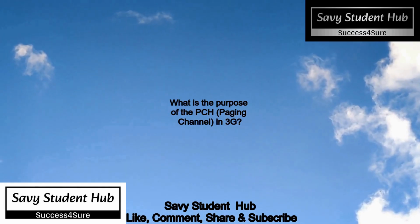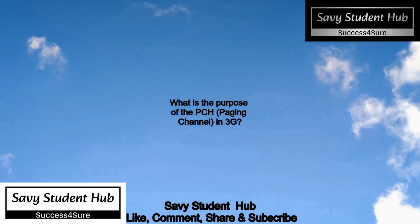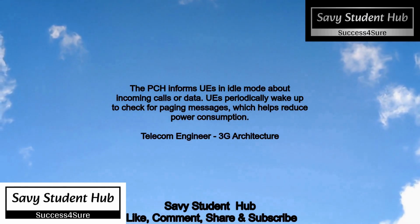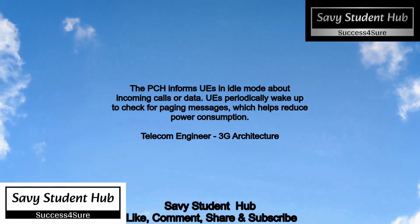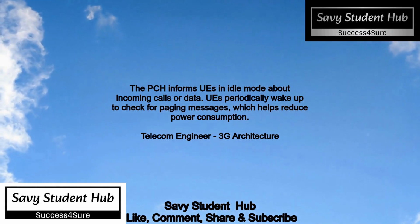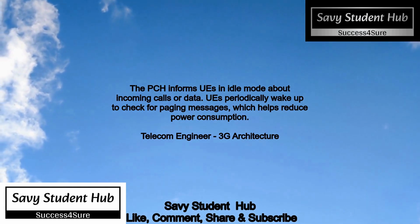What is the purpose of the PCH, paging channel, in 3G? The PCH informs UEs in idle mode about incoming calls or data. UEs periodically wake up to check for paging messages, which helps reduce power consumption.